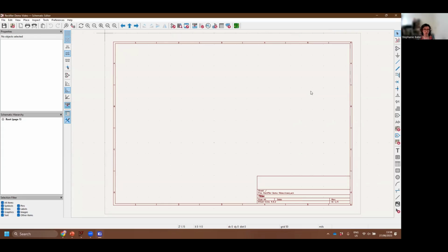And we've got lots of tools around our interface to look at as well. So I'll quickly talk through some of the important ones. The ones on the left are largely aesthetic. It changes the dimensions you're working in and stuff like that. Then across the top, we've got things like being able to edit those symbols. We can also browse the library of symbols. We can also edit footprints. Most of these things you won't be touching in this subject because the stuff we're using is all pretty conventional.